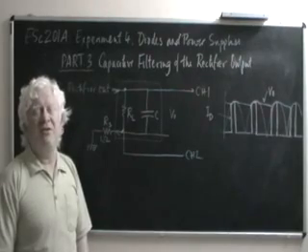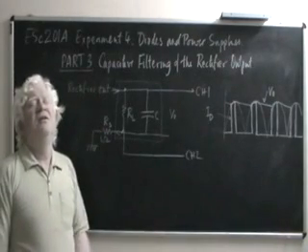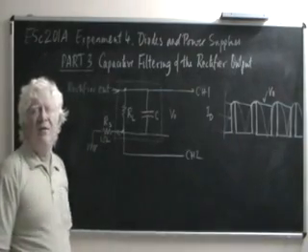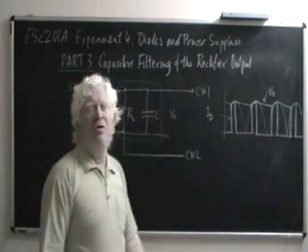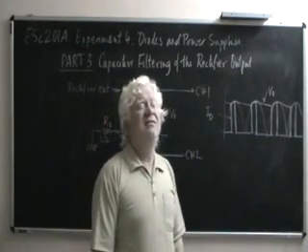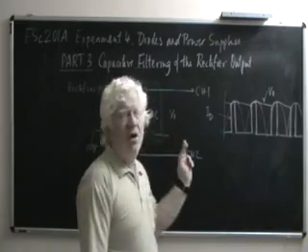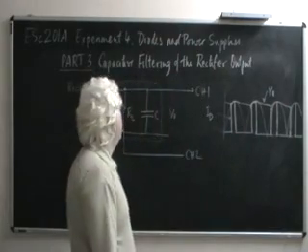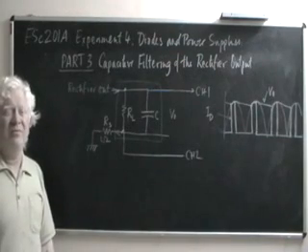So for a very large capacitance, when the diode gets forward biased, it is almost short circuited to the ground, except for Rs and some internal resistances of the diode. So the larger the capacitor you put, the stronger is the current pulse, the higher is the amplitude of the current pulse. This is a caution to us that putting on a very large capacitor would give you a very level waveform, but it takes you to the risk of blowing up the diode by excessive forward current in the diode.